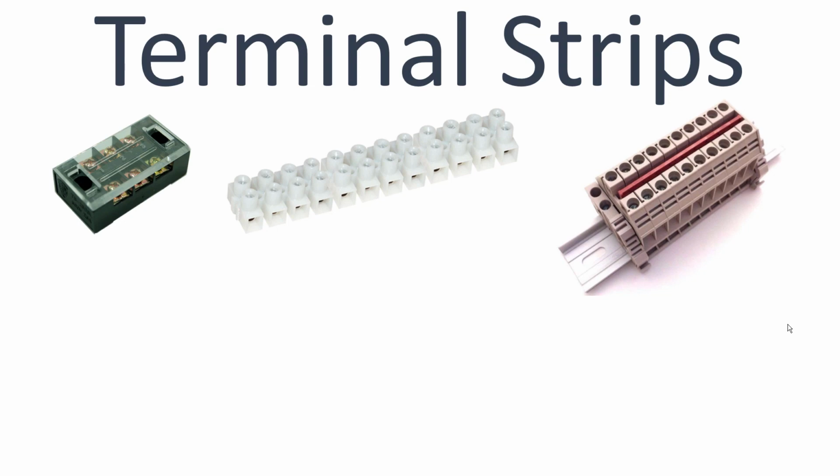Terminals. Terminals can be inside the enclosure or they can be outside if you build one similar to what I do, where I use that digital field device simulator. Then I mount the controller on a piece of DIN rail, and then I use regular terminal blocks like you see on the right to expand or extend I/O out and off of the trainer to external things that I might want to hook up to it, like sensors and things for playing around with the system.